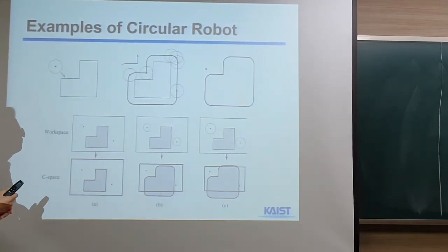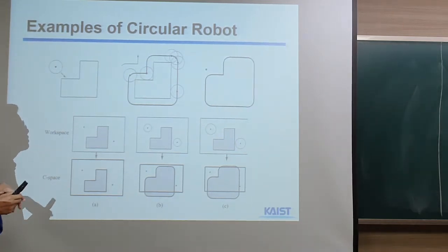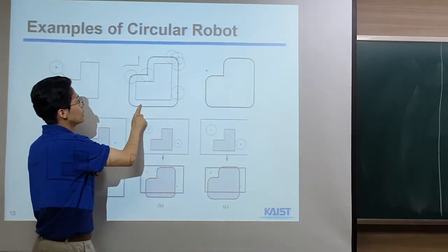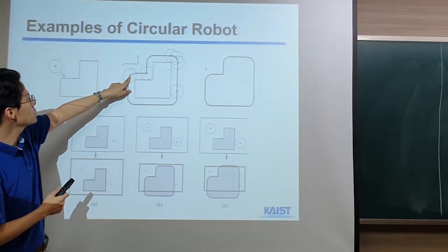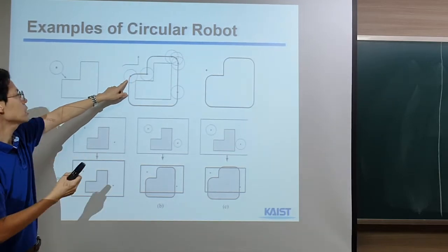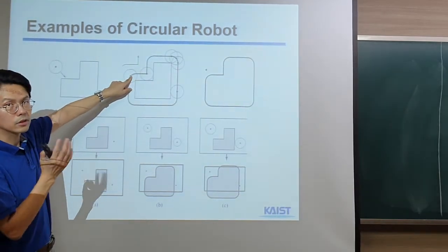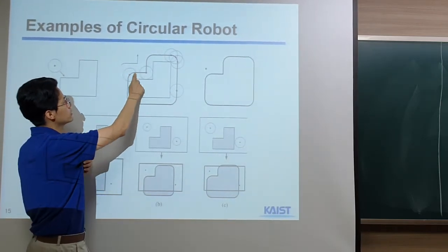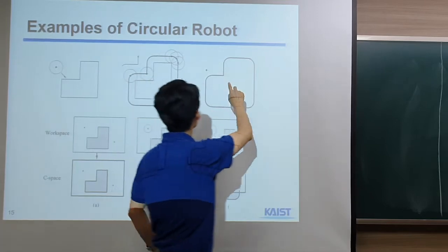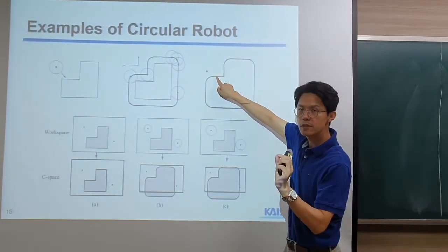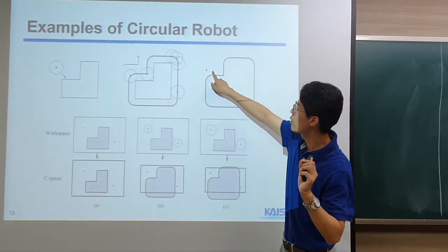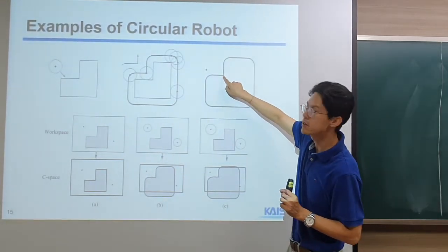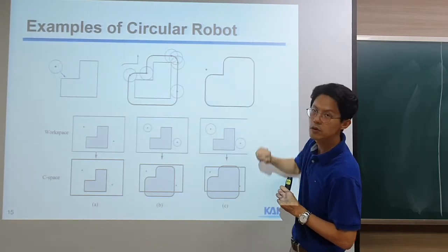And then to compute this C obstacle space where we have collision, one easy way is that we roll the circle from here to there, right? And then when you are looking at the center position, for example, this is actually our DOF in our C space, the XY position. Then if you look at the trajectory of the center of our circle, if we place the center of the robot there, we will have collision, right? So actually this is showing the boundary of our C obstacle. Within this space, we will have collision, right?